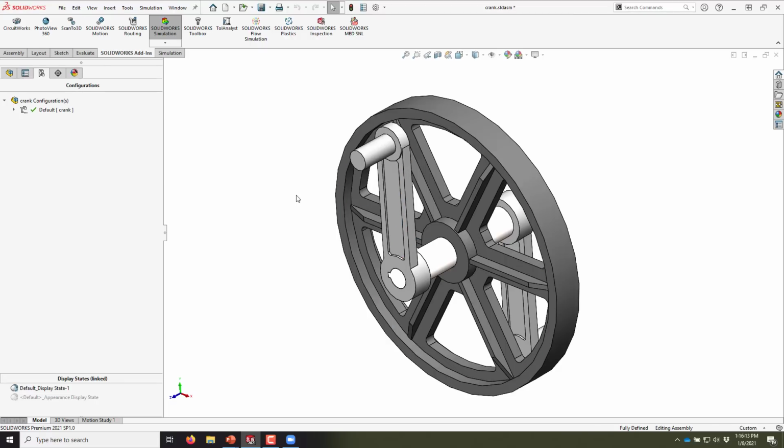To get started, we're going to create a new study to analyze the stresses on this arm. The kind of load case I'm going to be testing here, we're going to be putting 300 pounds. That's what I'm estimating. When we stand on the elliptical, it creates this 300-pound load. Maybe that came from some hand calcs or a motion study. I imagine 300 pounds put on this arm here. And I'm going to fix the belt location so that we can see the net torque that it's going to create on the arm. And then we'll do this, like I said, those two different ways, starting out with a simple just two-part assembly and then adding more components to it.